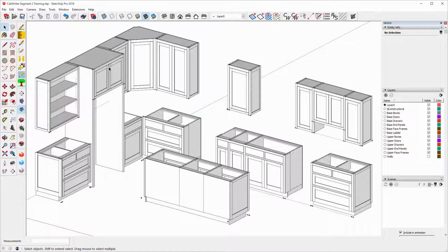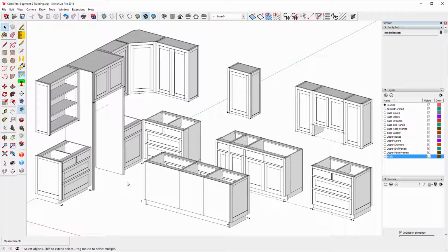All right, now, if you're pretty sure at this point that this is what you want for cabinets, you're not going to be editing them very much, but you've got some customization to do, this is a good point to go ahead and do customization. However, if you think the client is still in flux, or you're pretty sure there's going to be some cabinet editing, especially cabinets where you want to customize them, I wouldn't do that until things settle down. Because every time you edit a cabinet or use the command File, CabWriter, redraw all cabinets, you lose all of your customization and you have to do it again. So you want to make sure that the client is pretty well settled. That being the case in this project, I'm going to make the customizations that I have to make.